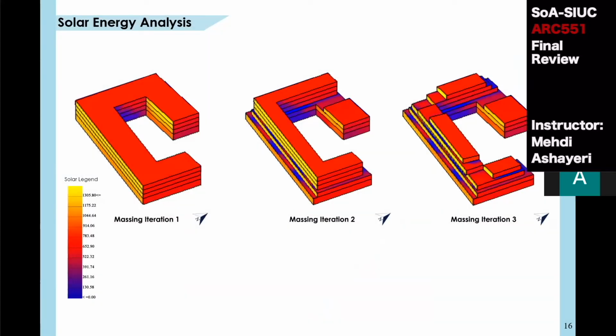The first one is the solar energy analysis that we did, and you can see how we went from the very first shape of the lot that we were using in the iterations and slides way back, and then we start cutting out, and as we run and rerun the iterations, you see how that helps mitigate some of that solar gain, because in St. Louis, you do not want as much solar gain, since their summers are much more dangerous than their winters.